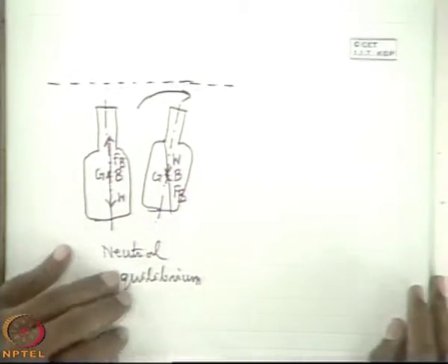So what we conclude is that when a body is totally submerged, the condition for stable equilibrium, that means angular stability, where the body is given a slight angular heel in either direction, whether it will come back or not, depends upon the fact that when G, the center of gravity, is below the center of buoyancy, the body has this angular stability, means stable equilibrium.